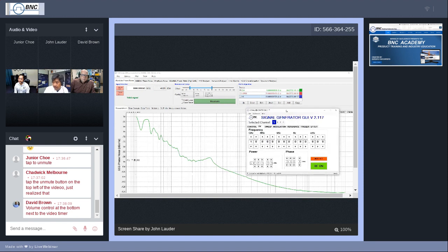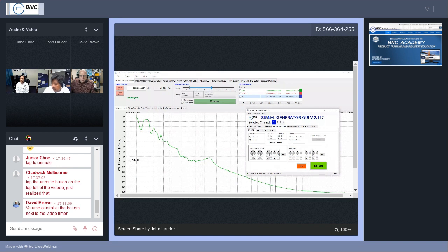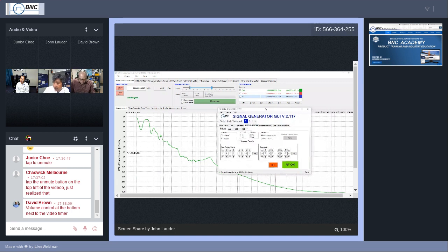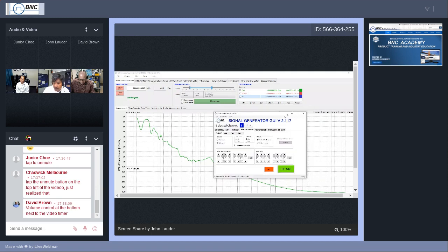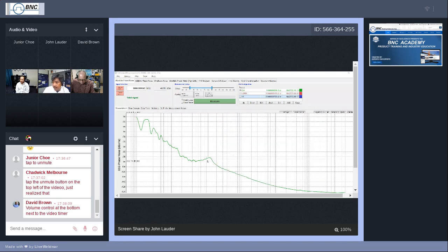This time I have a frequency of 10 gigahertz, which is in the X band, one of the most commonly used frequencies in radar systems. I also have my pulse generator set to a 50 microsecond rate and about 5 microsecond pulse width. That's about 10% duty cycle. I also made a phase noise measurement of 10 gigahertz CW, so we have some reference.